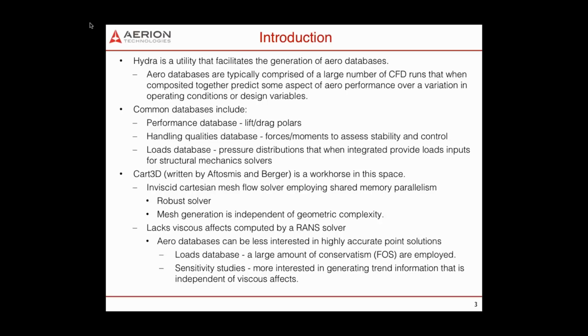They include performance databases like lift and drag polars that you've seen for years. But you can see other databases, like handling quality databases, where people are looking to assess or quantify forces and moments for the purposes of establishing the stability and control of the vehicle. Finally, you also see a lot of loads databases, where pressure distributions over a variety of operating conditions are integrated over structural panels on the vehicle, and these provide load inputs for the structural mechanics solvers for the purposes of assessing the worthiness of the vehicle structure.